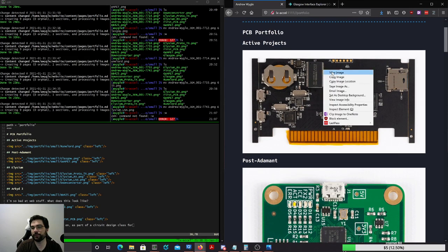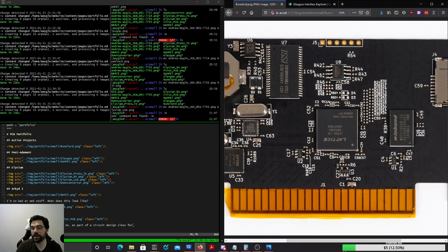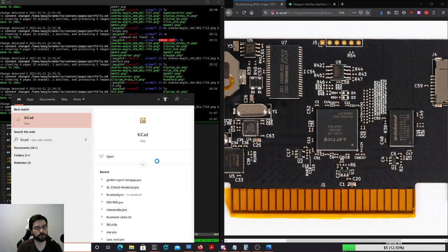So here, if we look at the image and zoom in, these are pins, right? But this chip has no obvious pins. And the reason for that is because it's a BGA. Instead of pins, there are solder balls that go under the package. You just heat them up and they bond directly to the board. And you can fit a lot more pins in the same package area, basically, because obviously the edges start to get crowded very quickly. This thing has 256 pins? So that's what a BGA is. And then a breakout is when you're routing a circuit board.